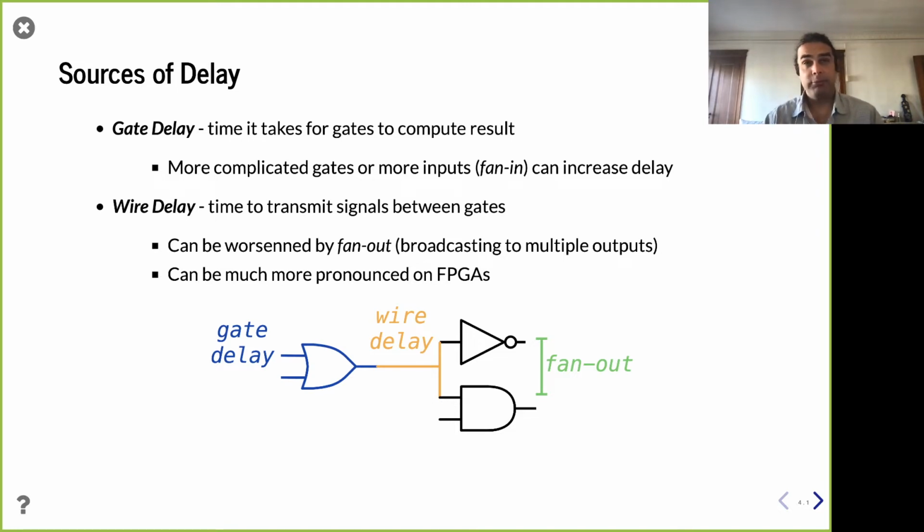And there are multiple sources of delay. To zoom out and broadly characterize them, we could say there's delay associated with the gates and delay associated with the wires. And the wires can be non-trivial, right? The wire is going to go a certain distance. Perhaps it's intuitive that there should be physical costs to these things. In order for a collection of transistors we call a logic gate to perform an operation, it takes some time for them to charge and discharge and perform the effective switching operation. And for a wire, it takes a certain amount of time to charge or discharge that wire.